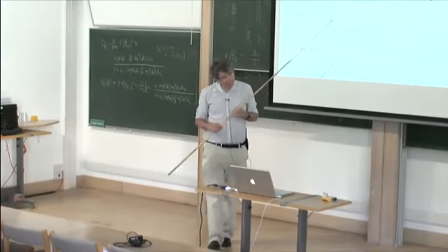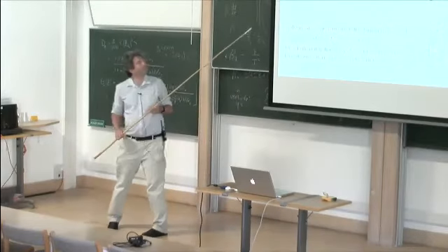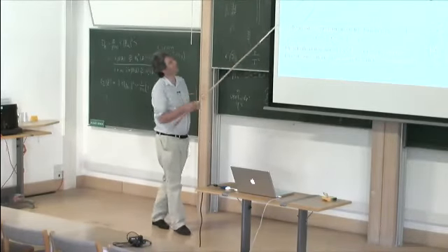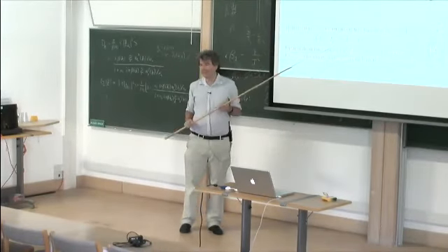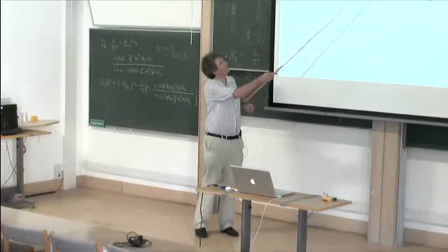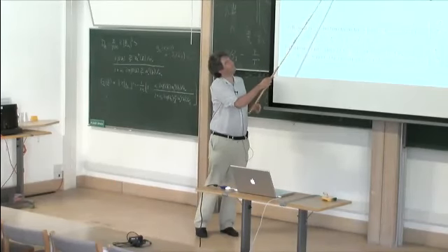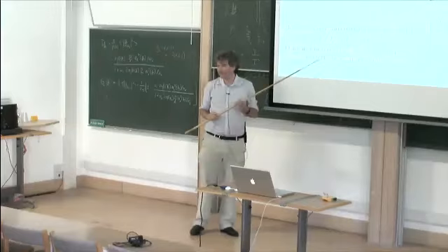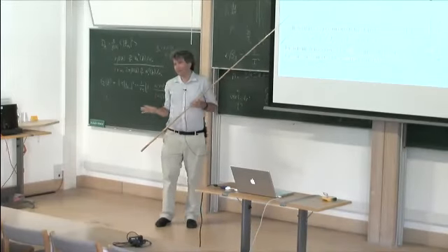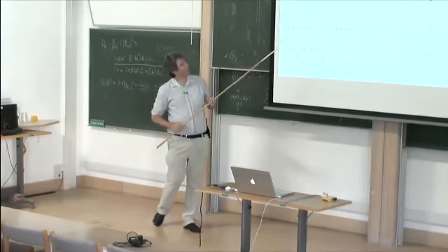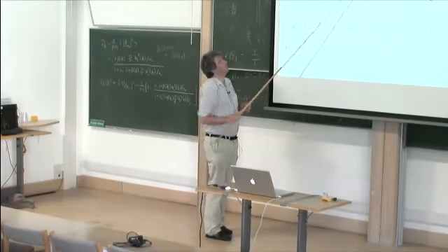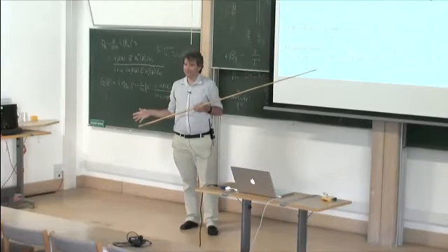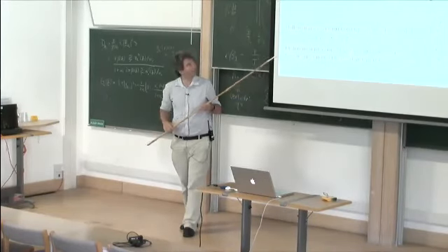So what's the motivation for doing it? The motivation comes from thinking about fluids 101, Newton's second law following a blob of fluid, then we can write down mass times acceleration is the force. But as soon as we stop thinking about following blobs of fluid but sit at a fixed point in space, we get a u dot grad u, something that's nonlinear, just because we have to map from a Lagrangian time derivative to a time derivative at a fixed point in space.